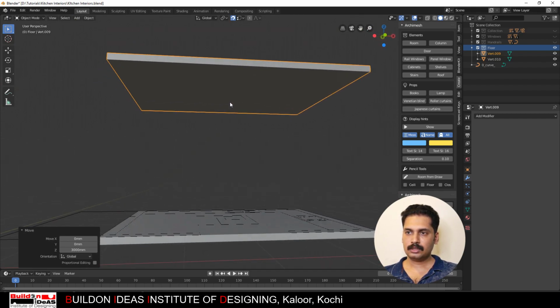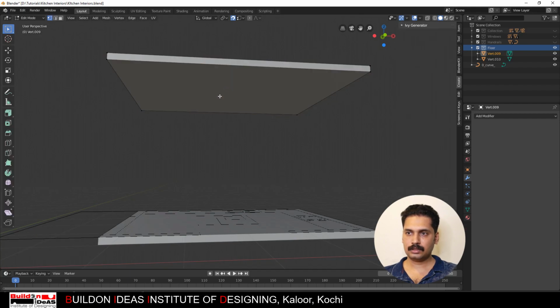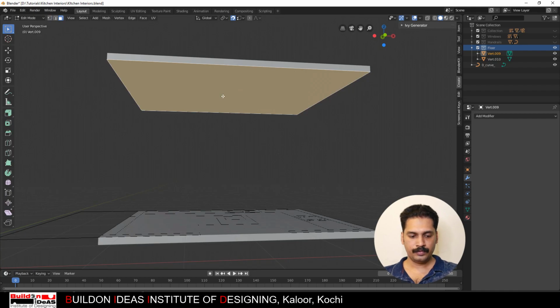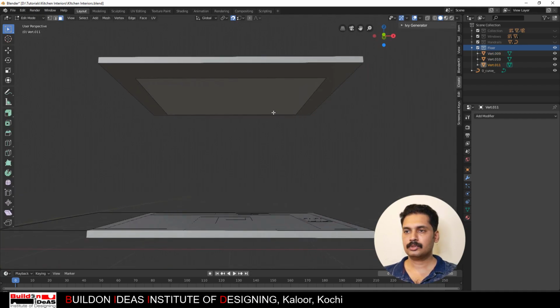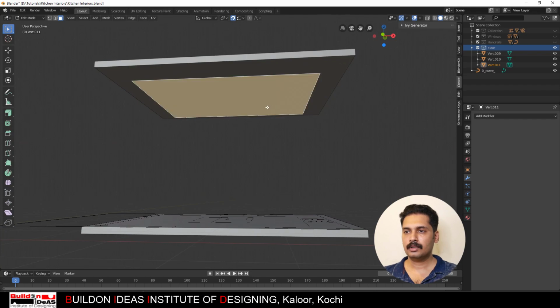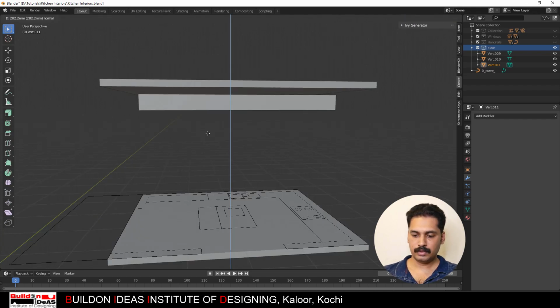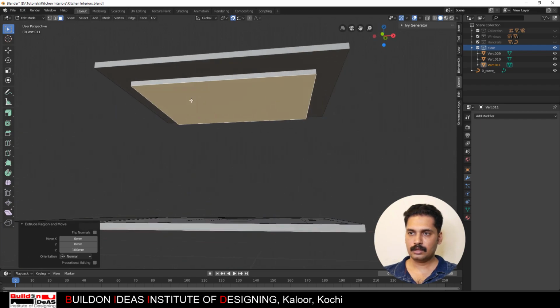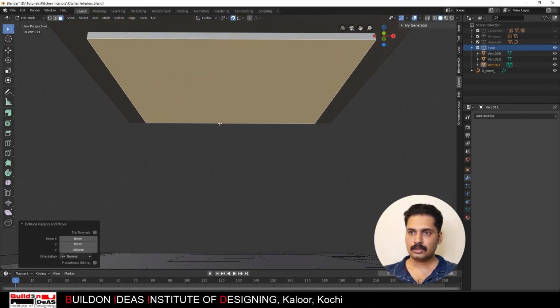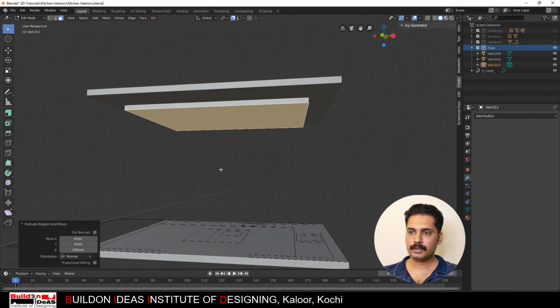this. So I'll just select a face of this, and then click Shift D to make a copy of that, and then press P to make it a separate plane. So I'm giving a 300 mm gap from the wall, extruded by 100. So you have a gap here in between, and then you have the ceiling. So that's how the ceiling is made by me.